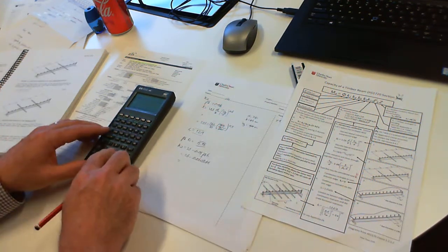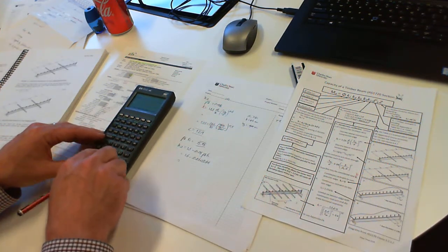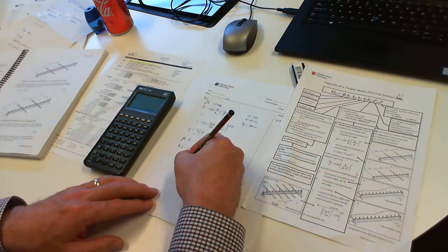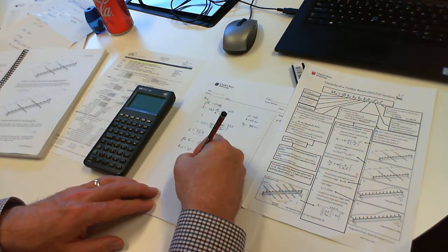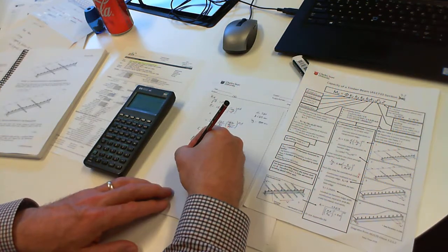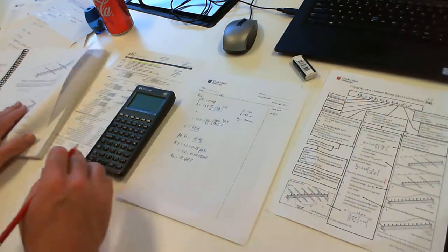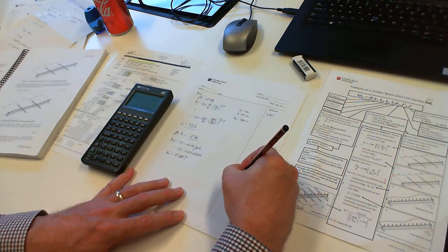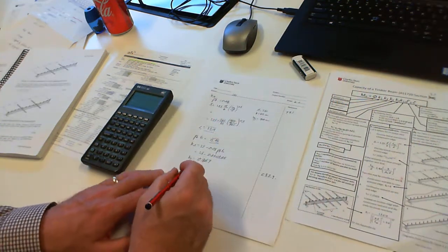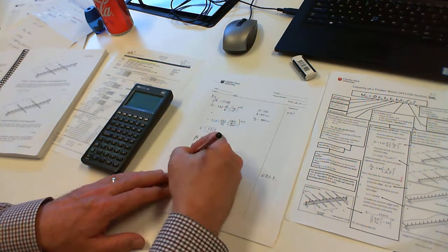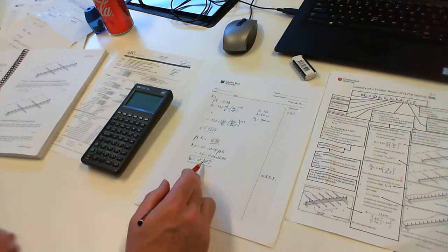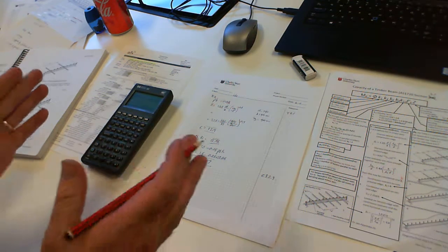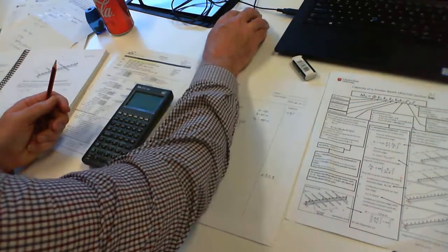And that equals 0.867. So K12 equals 0.867, and that's all from clause 3.2.3 in the code. So basically, the K12 is telling us that we can use 86.7% of the full bending capacity in this case because the beam's a little bit slender. All right, let's come back for part 5.